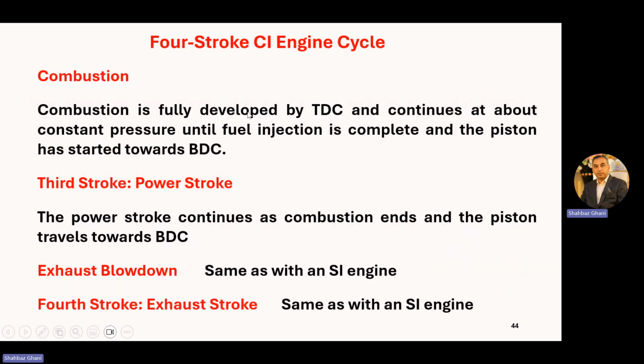Now, combustion is fully developed by TDC and continues at about constant pressure until fuel injection is completed and the piston has started towards BDC. Before TDC, the combustion started. At TDC, combustion fully developed. After TDC, the combustion completed.